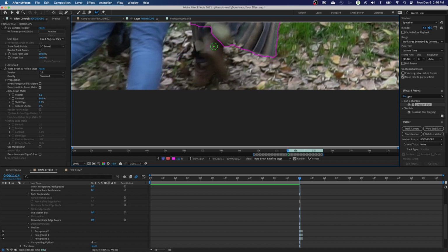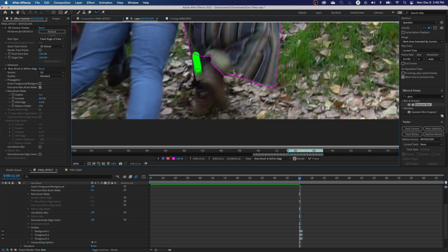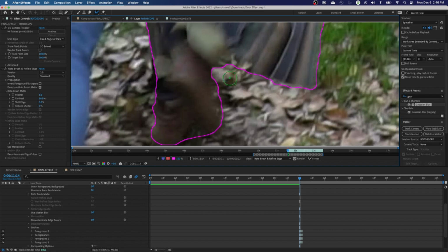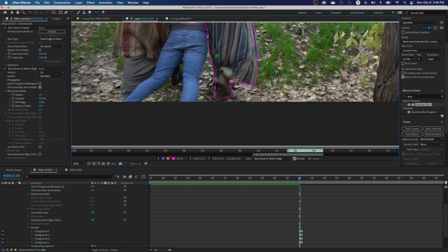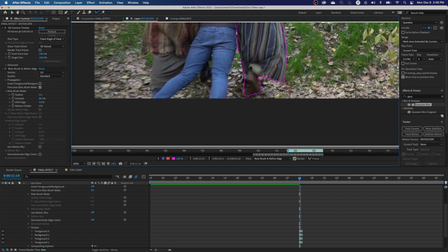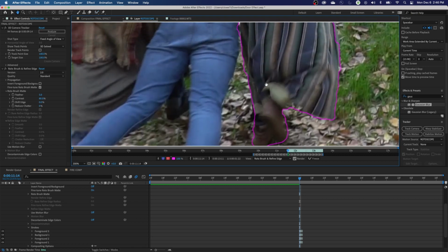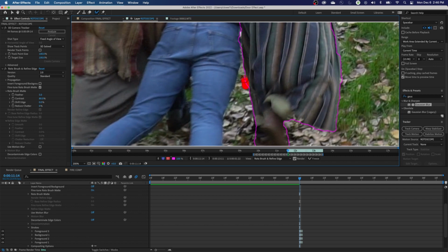And it's still not wanting to grab the foot, so let's add this foot in. There's his other foot. So okay, and this is where it'll do a much better animation the more you get this drawn in. The better animation it will do when it animates this spline, this moving mask. It'll be an animated mask essentially that moves with him, and it does a really good job of detecting most of the time.